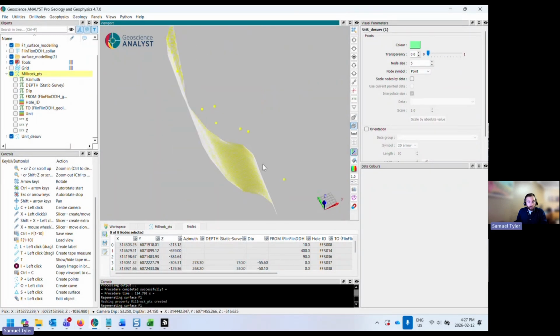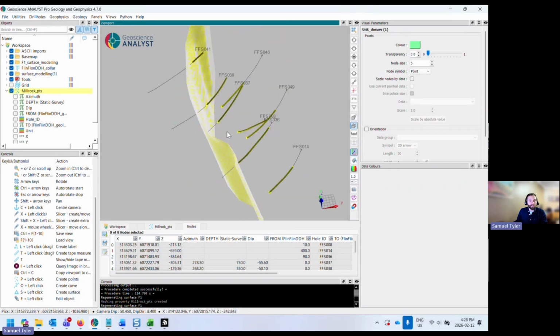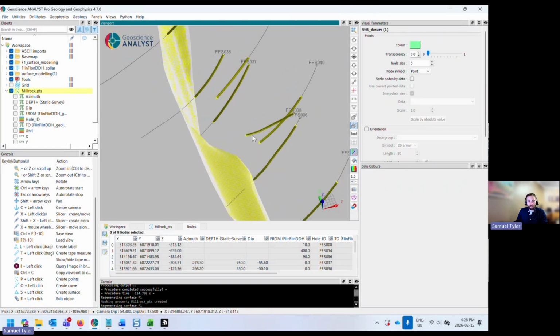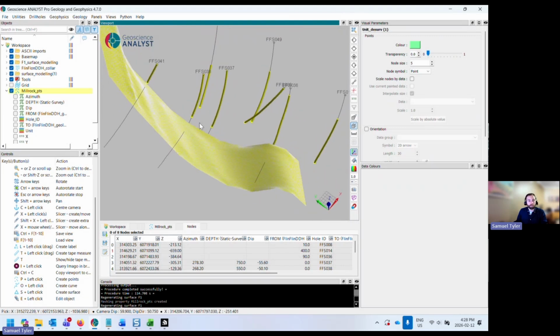There's something else wrong with these points that we do need to fix. Any ideas? No? That's okay. You'll need to turn on the drill holes to see it. So let's see, looking on my screen, these 2 points, would it be right to use these? So we need to grab those points that are actually at the end of the hole and delete them.